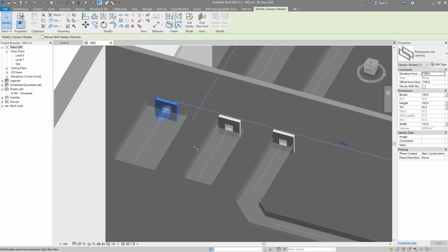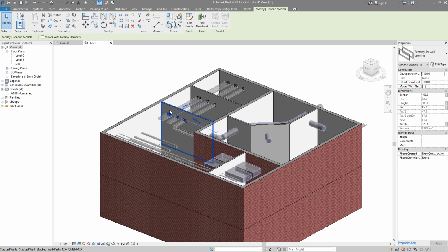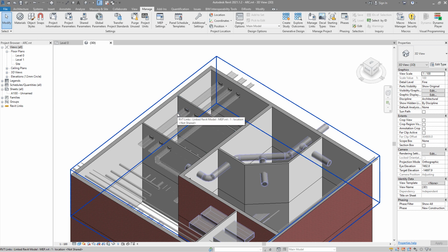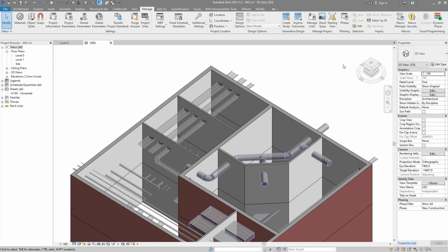So now, because originally I created the script by using millimeters, and now I did change project units, okay, you see that you have some results, but actually the scale of those results is not what you are expecting. Then just check on your side if you did change anything regarding the project units. But if you are using my project file, if you are using my script, that should work. But if you start playing in order to adjust my file according to your file, it's not enough just to change something in Revit. You must also adjust the Dynamo script in order to have the same results as I did have at the moment when I did run the script.